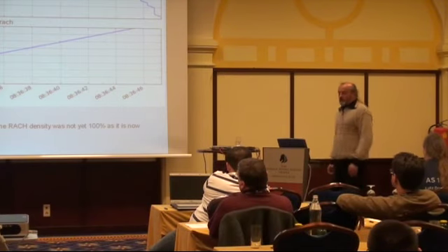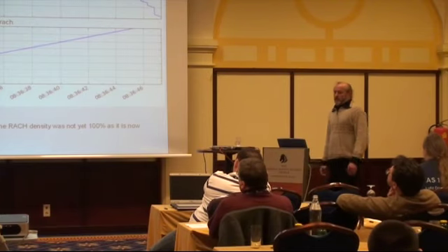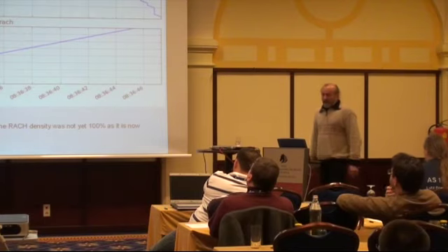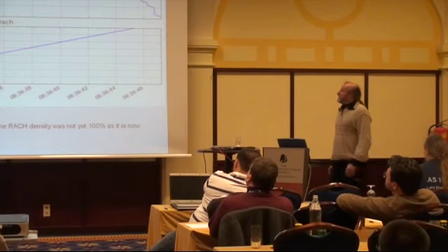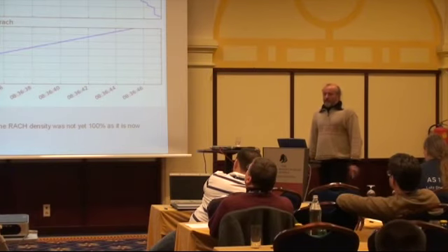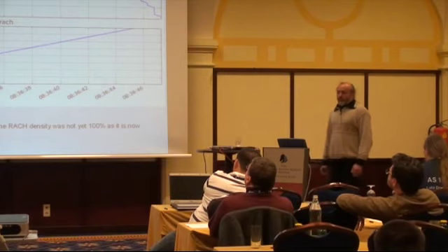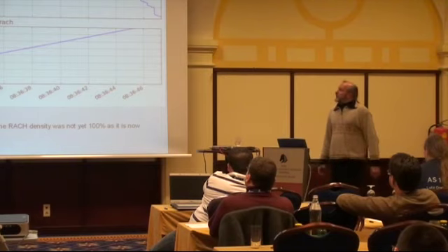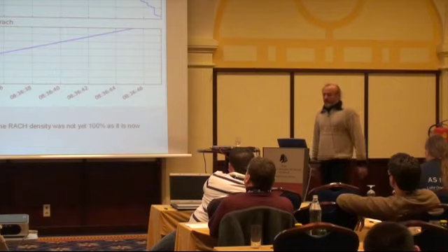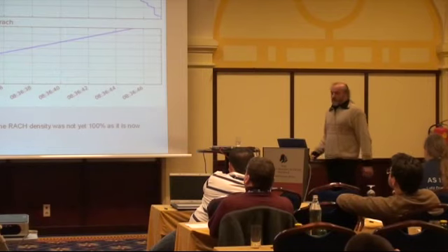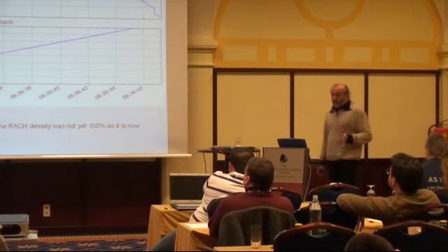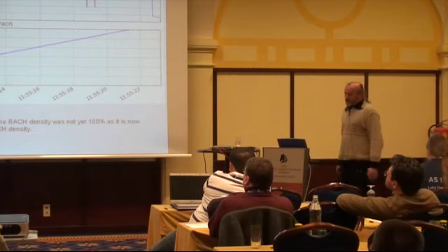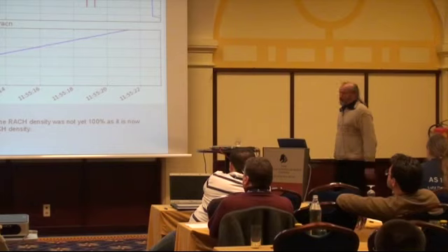This BTS in this diagram had 2 transceivers, and it was configured to have at most 24 channels. We can see in the upper diagram that these 24 channels are allocated rather fast. What was interesting in this experiment was that not each channel has its own timer to check for the expiration, but instead this base station controller periodically checks if channels have expired and releases them all at once. Those are those drops in the diagram. At every drop, the base station controller checks, are there any channels which have expired? Let's free them. In the next diagram, it's rather similar, but a different BTS, in this case 4 TRX, 40 channels available.